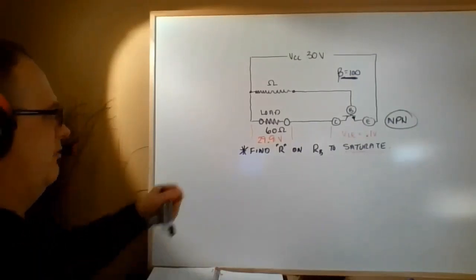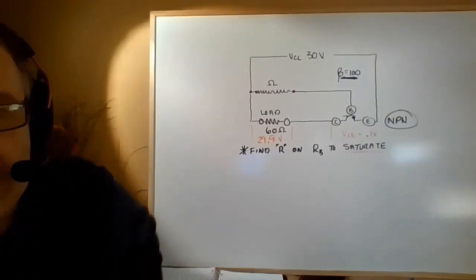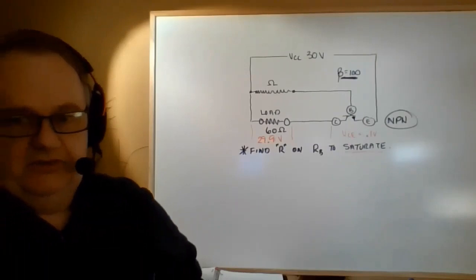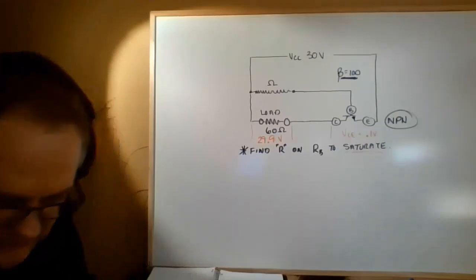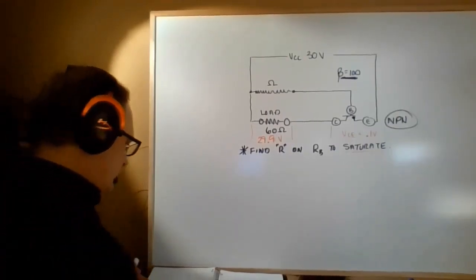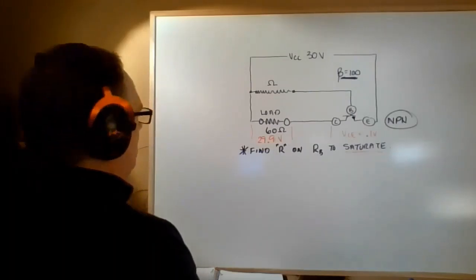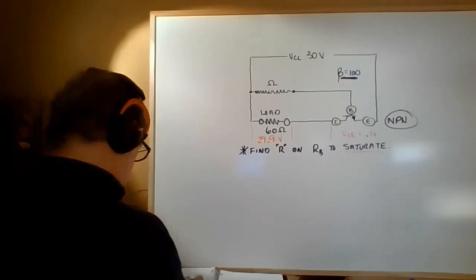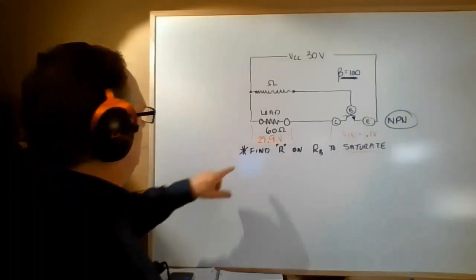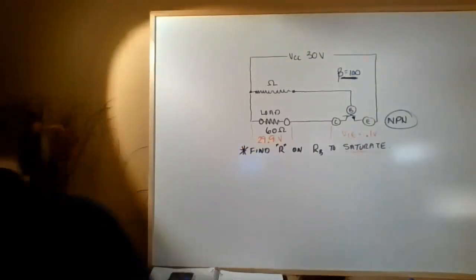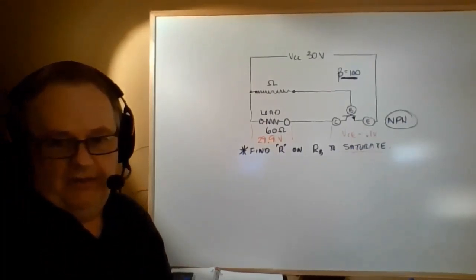So it's always a play. Remember, that's a series branch. We call it the load branch. And so really, if your lowest, fully conducting voltage across the transistor is 0.1 of a volt, then that leaves the 29.9 there. And that means that I now have an absolute maximum amount of current, okay? And that will be what we call IC, and that will be based on essentially the 29.9 volts and the 60 ohms. And I'm gonna quickly grab a calculator and run that through.